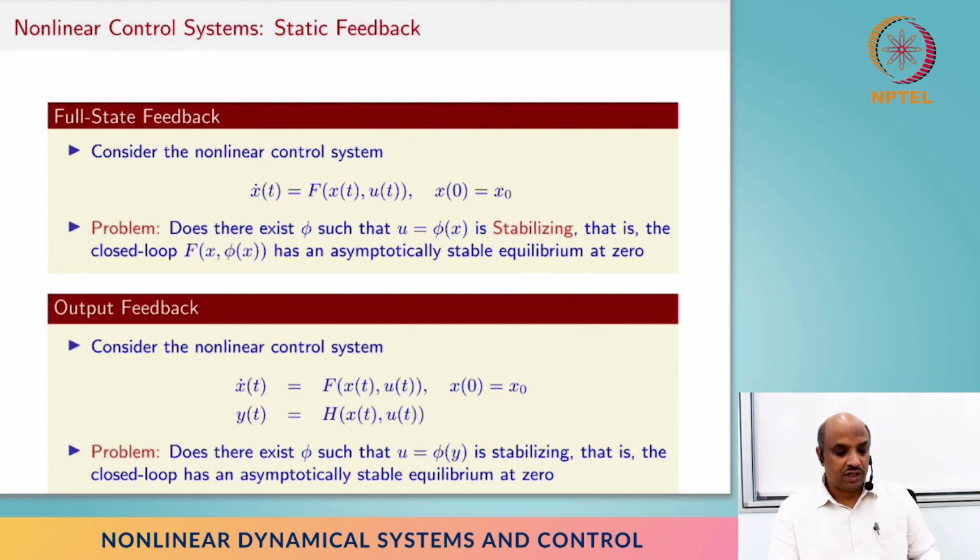But in reality, most of the time we do not have access to the entire state. Just a simple example, suppose you are trying to control the surface of an airplane wing or something like that, it's an infinite dimensional system to start with, and you can only control at a finite number of points. So there's no chance in certain cases to basically get the entire state. So you have a choice of basically assuming that this system is finite dimensional, and hopefully the infinite dimensional parts are approximated by this finite dimensional one, and then hopefully it is fine. Technically we call such things a projection of an infinite dimensional system onto a finite dimensional one, and then we work in the finite dimensional and hope for the best, right? So that's one way of thinking about it.